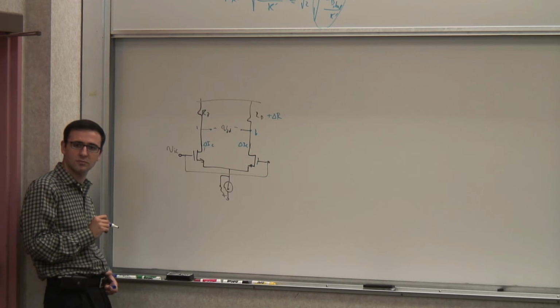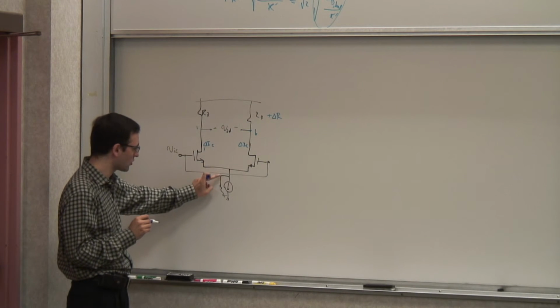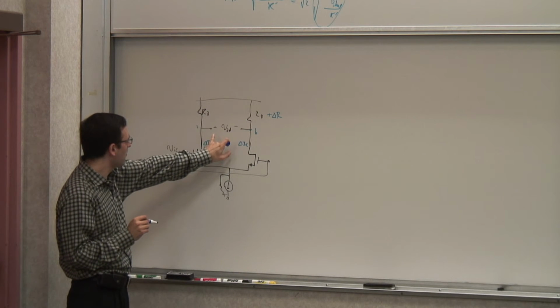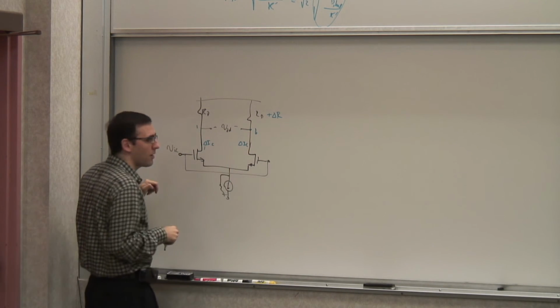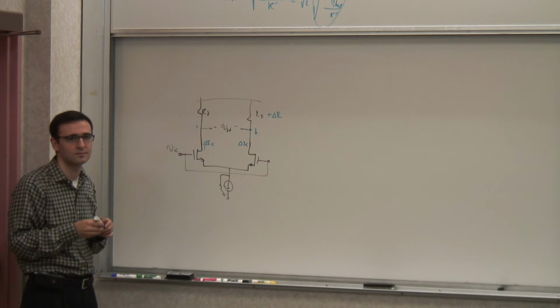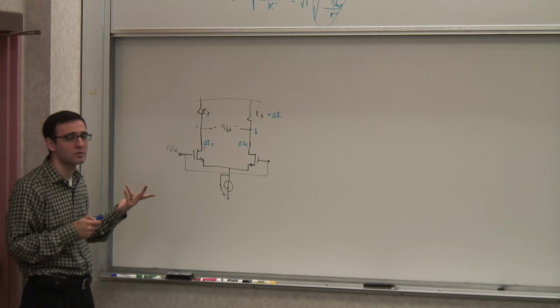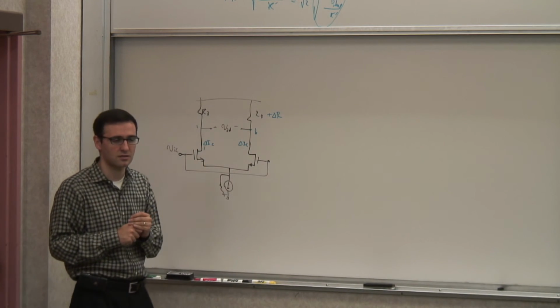Make sense? Let's say I apply this, there will be a change in the current because there will be more current flowing into this side. This voltage goes up. But for the same change in the current on both sides, there will be a larger drop on that side. So I've created a differential signal. Correct? So this is the basis of the common mode to differential conversion. And that's why matching of the two sides of the transistor is quite important.